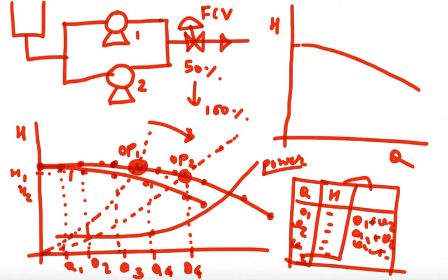So that means when you are operating the pump on the right side of the pump curve, your power consumption also increases and your NPSH also increases, because the NPSH curve is also similar to this curve, like this. This is NPSHR, that also increases, but the gain is higher here.